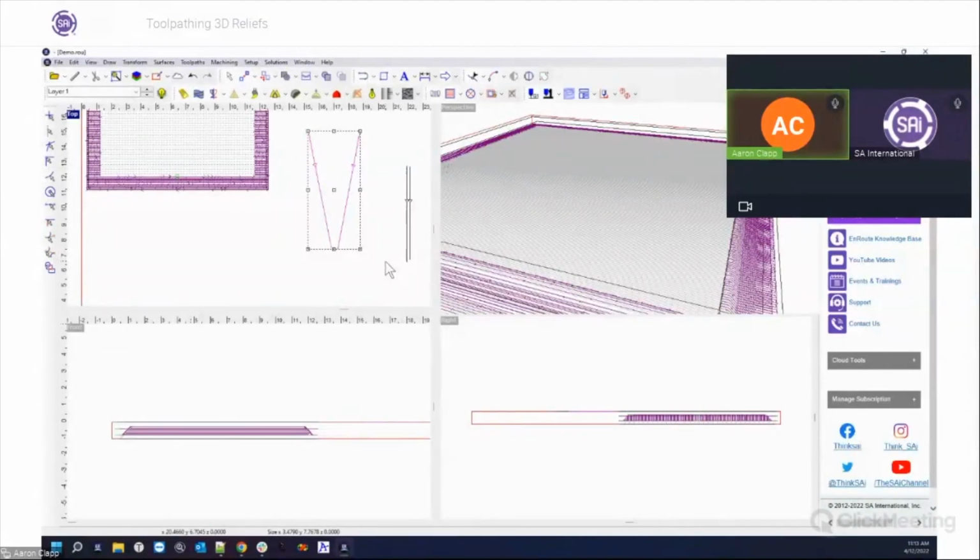And then in terms of your other sizes, like your quarter, 3/16, all those are strong enough to handle pretty much anything for the most part. So you could just get a standard ball end mill and you'd be fine in terms of that. So I would just have a good variety of stuff so that when you have a need, you can say, well, I've got a variety of tools to help me with that. But the ball end mill tools are going to be the ones that create those surfaces. Regular end mills can't create these 3D style surfaces. So that'll be just something to note.